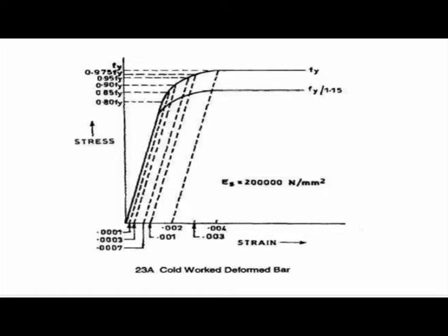Now in this one, 8 millimeter stirrup. Now what is the area of steel? Pi by 4 d squared, so I get the value for 1 bar. Here I have 2, this is two-legged, so it will give me the area of steel ASV. Here ASV, then I require the spacing SV. So for the beam I require bars. Just consider how many bars to consider.